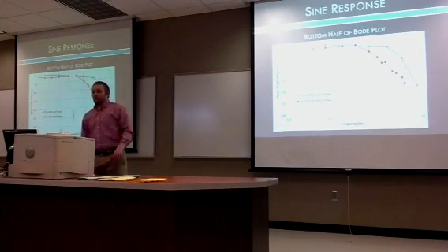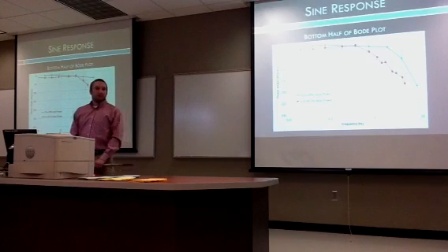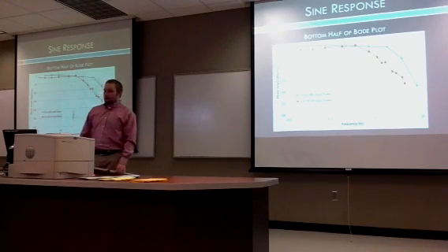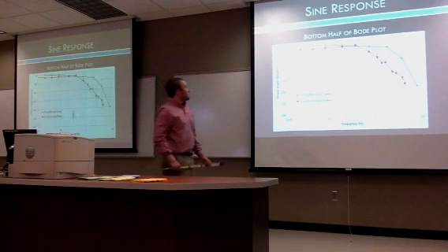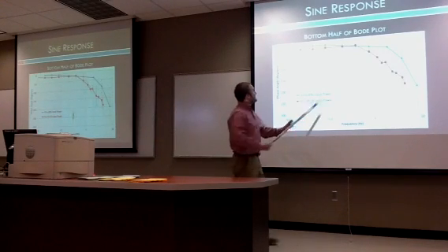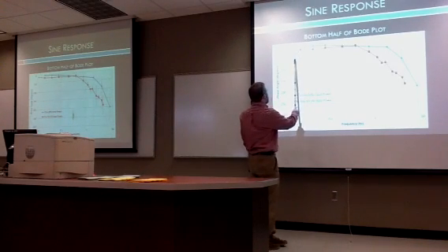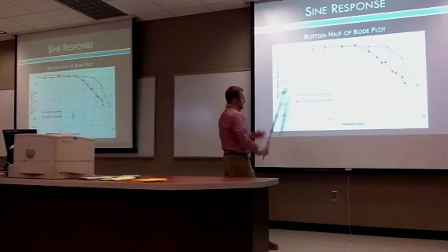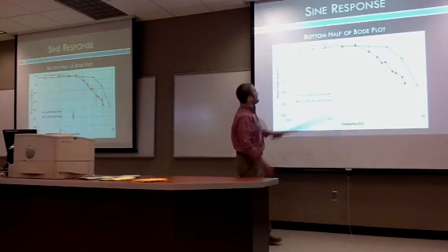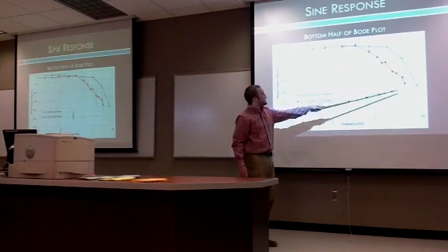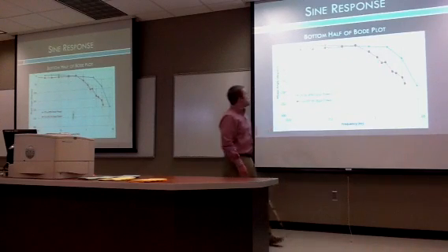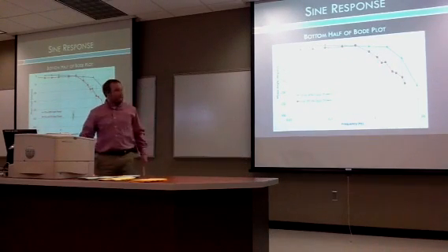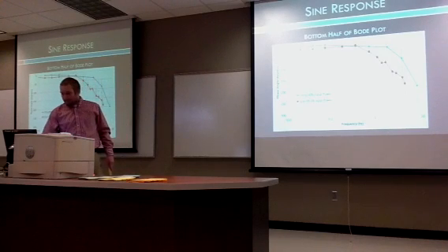For the bottom half of our Bode plot, it measures the phase angle versus the frequency. You can see it looks relatively constant for the 0 to 69% input power in red until it hits about here, and then it trends downward, and the blue is constant maybe to here and then trends downward. And that's for 70 to 80% input power.